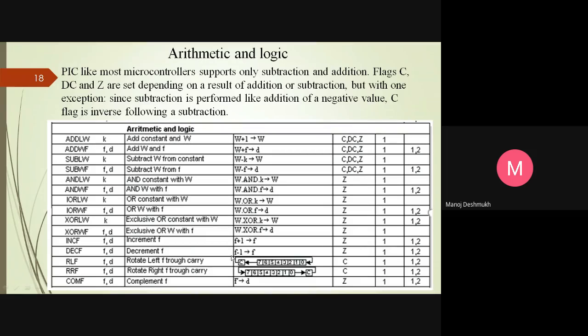So when we shift the total 8 bits, that is lower nibble to higher nibble like this, in that case your carry flag is automatically flushed out, that is, all 8 bits are rotated and again it comes to the carry bit as it is. But if we want to shift or transfer just 1 or 2 bits, in that case your earlier position of the carry may be affected.